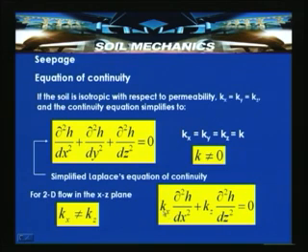then we can say that kx into ∂²h/∂x² plus kz into ∂²h/∂z² is equal to 0. So, here we can say that for a two dimensional flow in the xz plane, kx is not equivalent to kz.